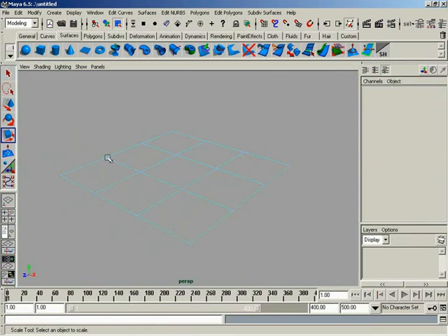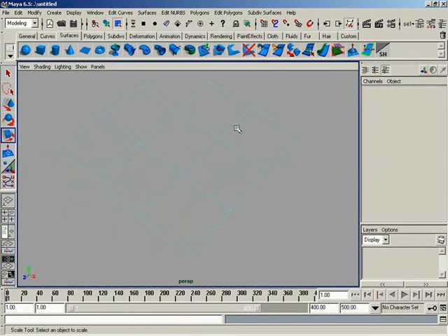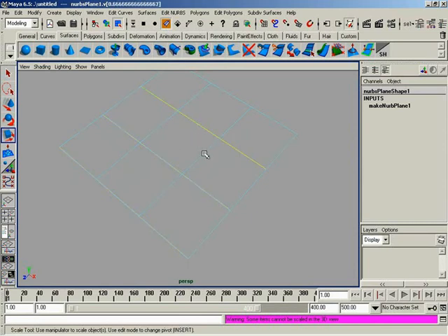Our isoparms are these lines that are running back and forth along the surface here. Except when you activate isoparms, you get an isoparm marker so that you can basically mark any place along a surface. Let's go up here to this particular pick mask. If I right-click, you'll see NURBS isoparms. Let's go ahead and activate it. Now you'll see that I can come in here and I can click on these bluish-colored lines, and they turn yellow. But I can do something else that's quite cool. I can click and drag.